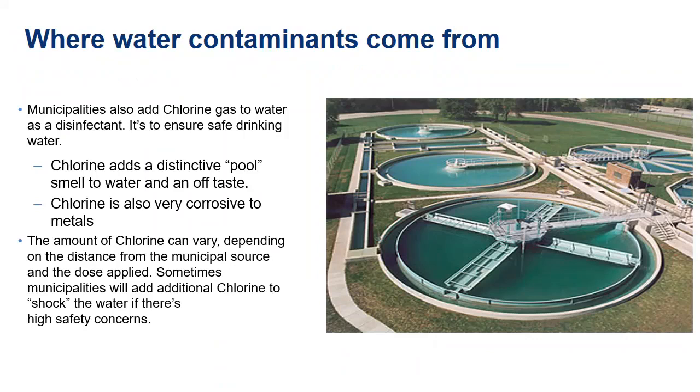Other compounds that are introduced at municipal water treatment plants tend to deal with particle load management, dirt load management, and those are flocculants and coagulants. These are added in excess, and quite often these will make it downstream in the distribution system to your dispense point. Well, these flocculants do not stop working. They coagulate particulates together and stick them together and they essentially make any filter after them more efficient at removing debris, which can lead to premature clogging of filters.